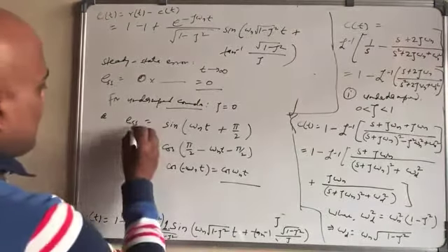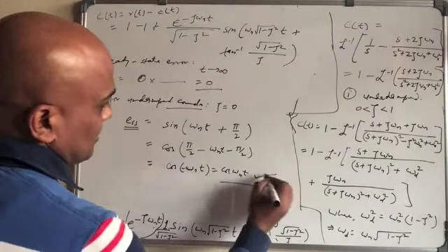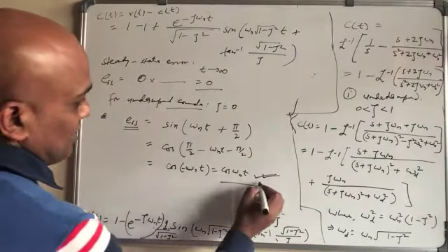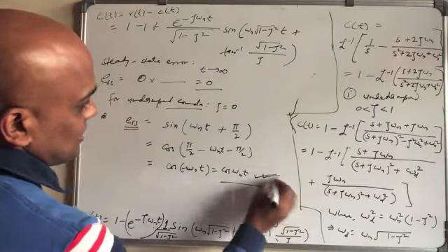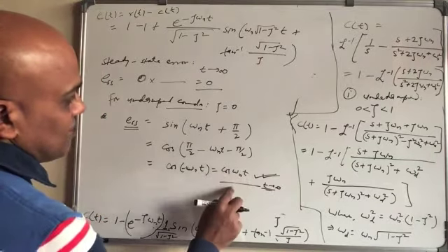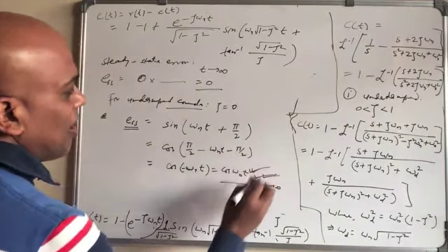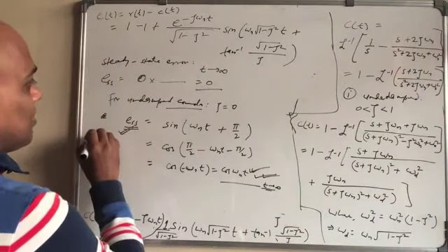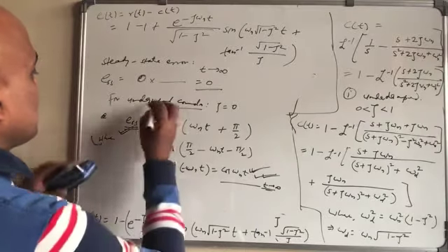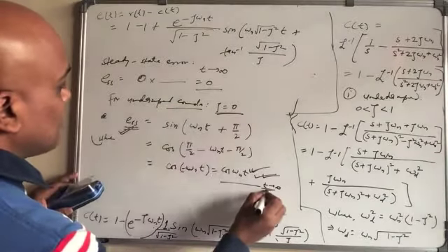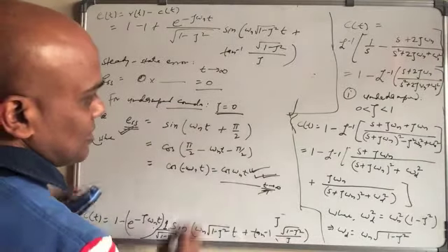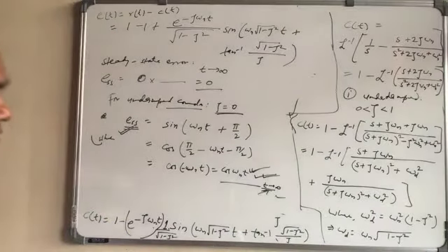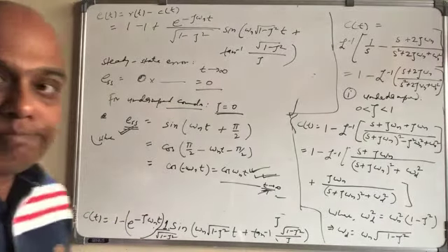So steady state error is never 0, so this becomes a function of time. Even if time tends to infinity, still you cannot take a limit of that, so this is actually oscillating. So when undamped, when zeta equal to 0, there will not be a zero steady state error. That's what it tells.